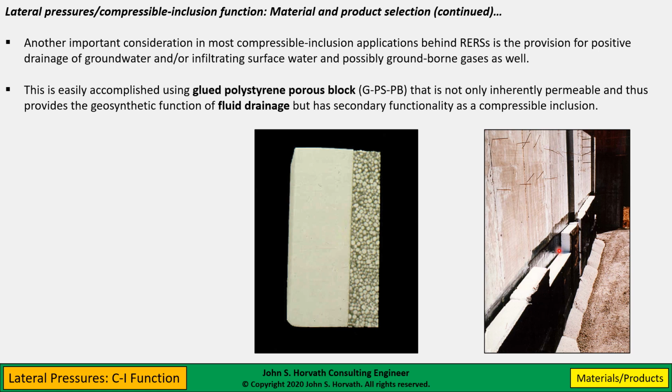And this one product is going to reduce the lateral earth pressures from the at-rest to the active state. It's going to provide thermal insulation for the below-grade space of this building, and it's going to handle any groundwater. You see it keyed into a drainage layer of crushed rock here.